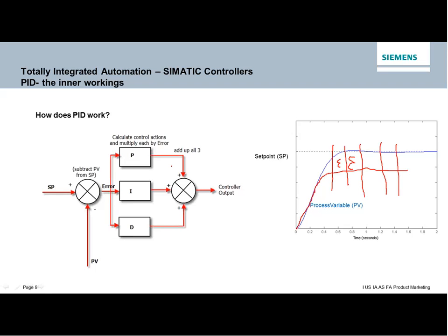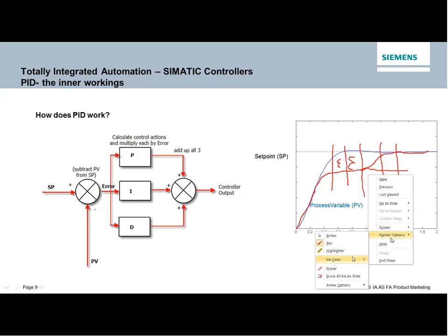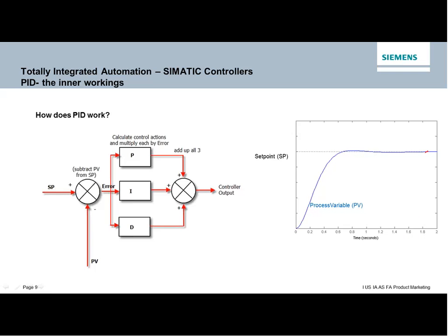And eventually with a PI type of algorithm, we're going to be able to bring this up and our error should go away. We have a nice little system that looks pretty much like that. So we should have a nice startup. It comes up to set point, levels out, and a PI algorithm can work for a lot of applications.